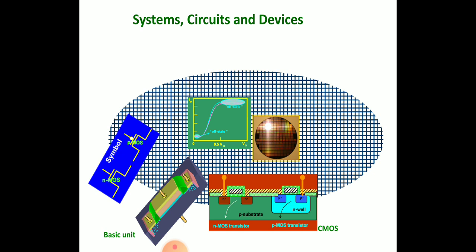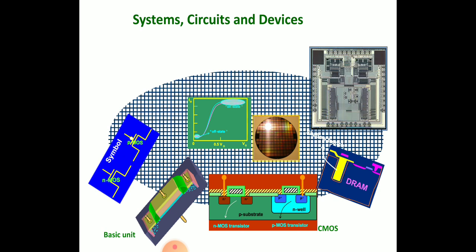So for digital design, I am giving you a CMOS perspective. In today's information age, you have to store all the data. Once you think about storing data, you require some sort of memory devices. For memory devices, you have to build the founding memories, that means the DRAM and the SRAM. What are those? The dynamic random access memory as well as the static random access memory. I am giving you a pictorial representation of a dynamic random access memory. Basically, it's based on a combination of CMOSs or different sorts of MOSFETs. Why am I going to memory? That is because of the memory storing element, the data storing element.